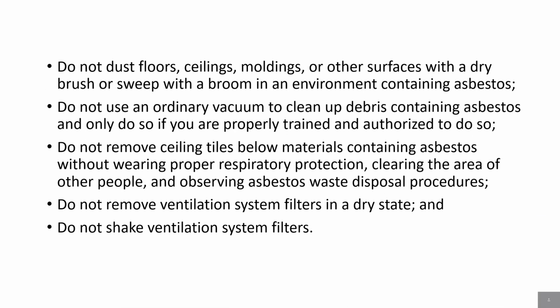Do not dust floors, ceilings, moldings, or other surfaces with a dry brush or sweep with a broom in an environment containing asbestos. Do not use an ordinary vacuum to clean up debris containing asbestos, and only do so if you are properly trained and authorized to do so. Do not remove ceiling tiles below materials containing asbestos without wearing proper respiratory protection, clearing the area of other people, and observing asbestos waste disposal procedures. Do not remove ventilation system filters in a dry state, and do not shake ventilation system filters.